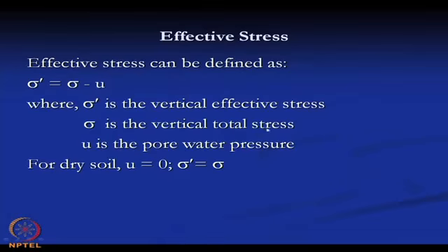Now, if we permit the water to flow, then gradually this water will flow out and the stress which was taken by the water initially will be transferred to the soil skeleton. As time progresses, the soil will take the stress in that fashion.